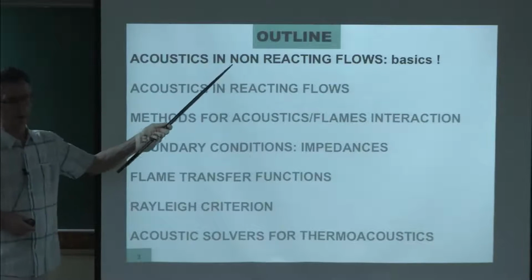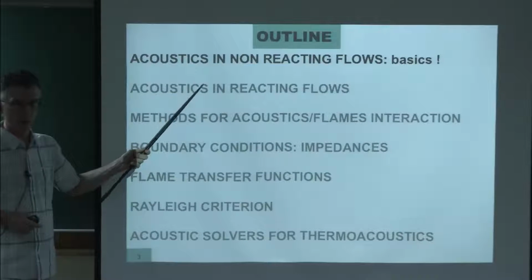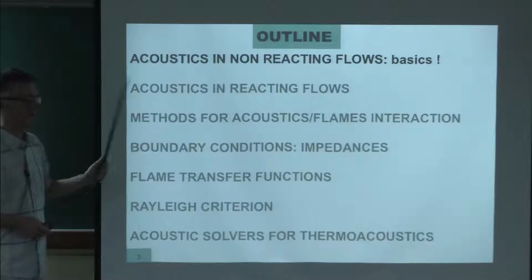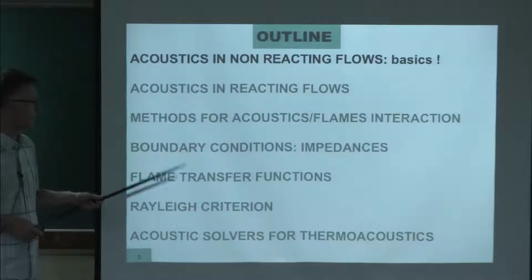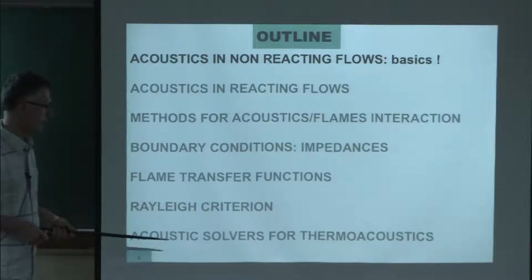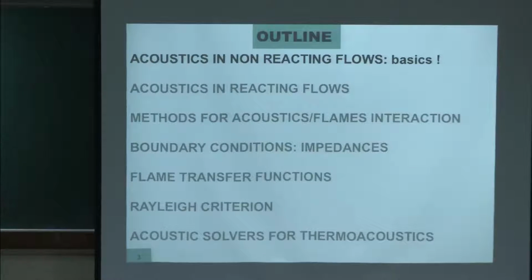I will do acoustics in non-reacting flow, then we'll go to flames, acoustics in flames, which is an interesting topic. And I will show you the methods to look at the interaction, the boundary condition, the impedances, what we call flame transfer functions, the Rayleigh criterion, and I will then describe the tools which are needed if you want to study combustion instability. Some of these tools are extremely simple. They correspond to theory, like those I have described during the seminar. And some are, of course, extremely complicated, like LES. And there's a whole range in between.